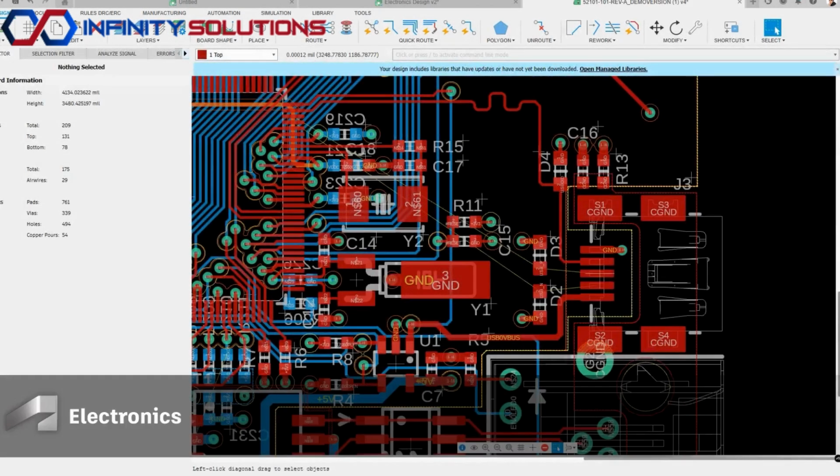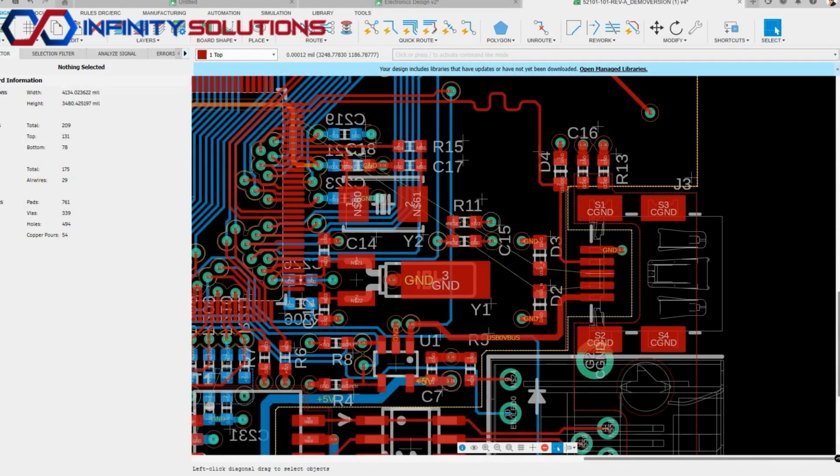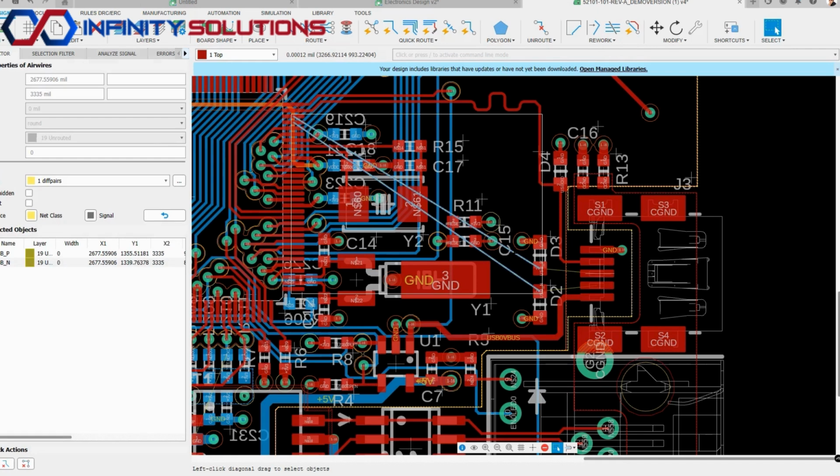We've delivered a long-awaited feature in electronics, the ability to color code nets and signals to simplify routing tasks. This can be activated or deactivated using the Shift and A key combo, which reveals the color coding. In the inspector, you'll notice the new appearance parameters. These allow you to define a color for special signals.